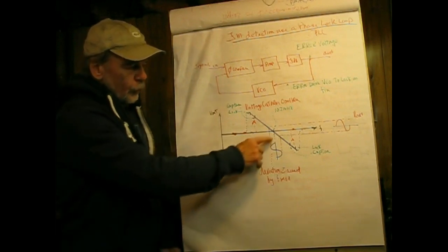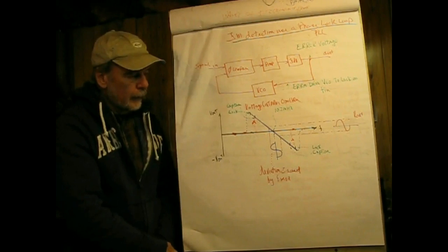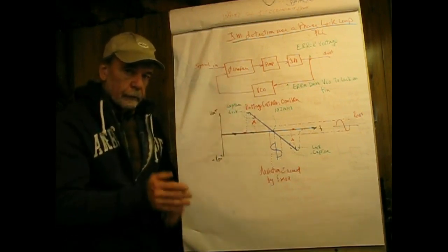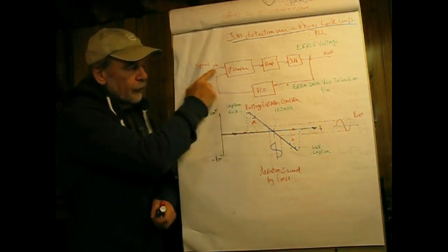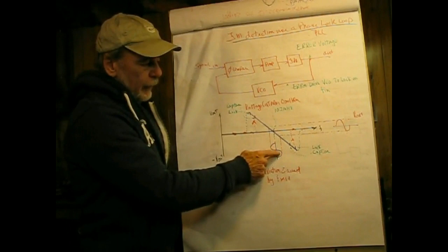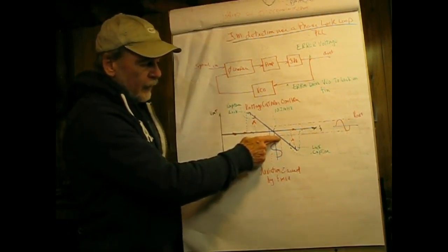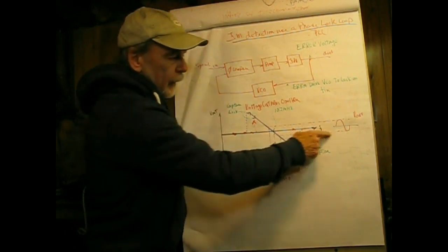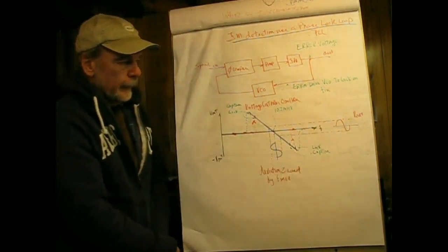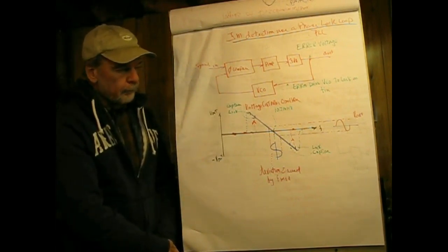Lock occurs, we're sitting here, and let's just say we don't have any errors in the VCO and the phase comparator. The free running frequency of this is very, very close to this. Now as the signal deviates, I can do a projection off the voltage controlled oscillator characteristics, and from that projection I can see that the output voltage is going to be a function of the modulating voltage, just like before.